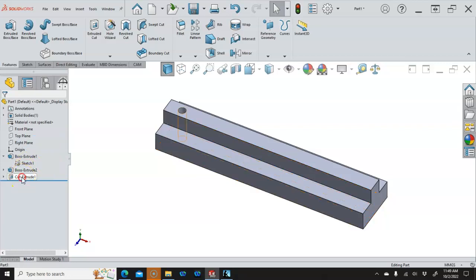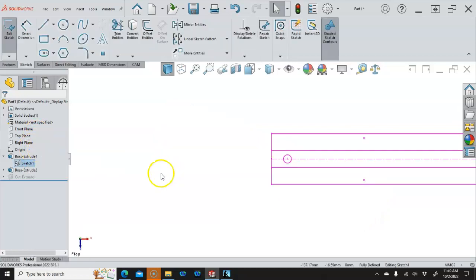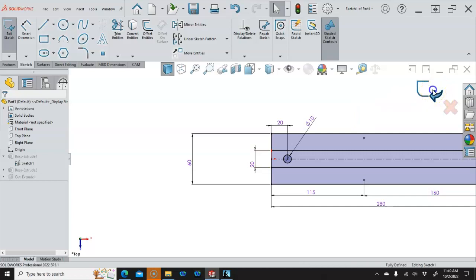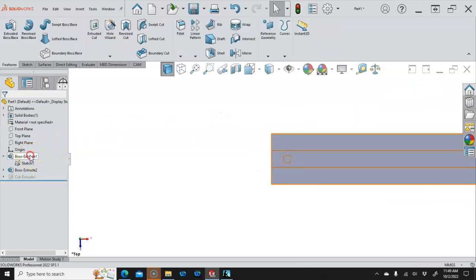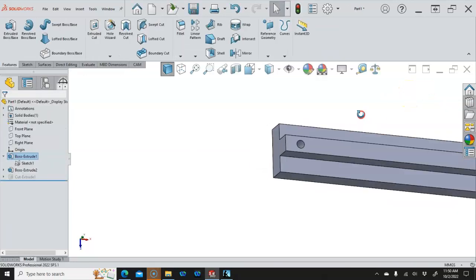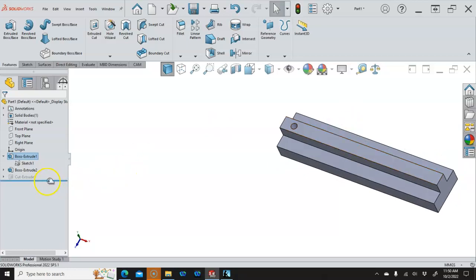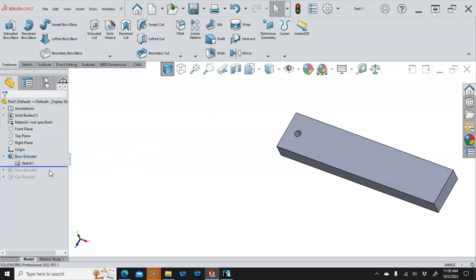Then the other solution, let's go ahead and suppress. The other solution is just to edit the first sketch that had the contour. Oh, take that back, edit the first feature. And in our selection set down here, we have sketch contour 1. And if I add that to the mix, that will also make it so the hole exists before we do the other one.